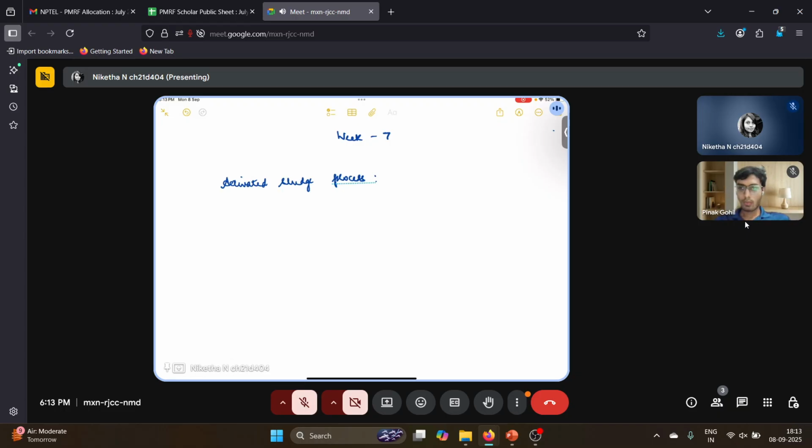Okay, the activated sludge process is a type of secondary treatment where the microbes are suspended and not stationary. So what do we mean by activated sludge? When we have a tank full of microbes degrading organic waste, once the microbes reach a certain level of population, they start eating themselves because beyond that they don't have any waste left, and they enter a stage of self consumption.